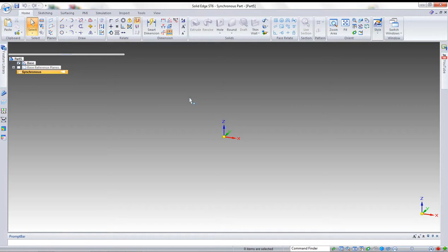What that means is that your design processes need to also align with your manufacturing processes. More graphically, if you are working with sheet metal, then your sheet metal needs to lie on the XY plane as much as possible.